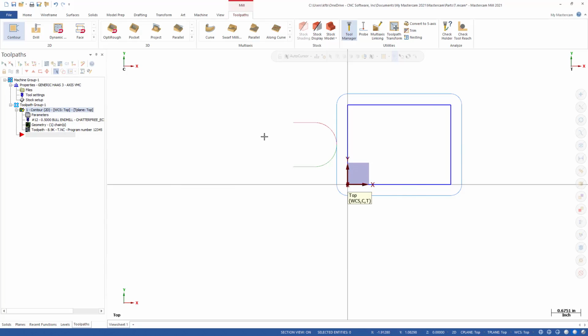Now we just edited the projection of that assembly in this Mastercam file, but just realize that that only changed the projection for that assembly in this file and not in the actual database. If you wanted to update that projection for all future uses of that tool, you'll have to do it in the database. In the next lesson, we'll explore the steps to create a new tool using the Mastercam Tool Manager.